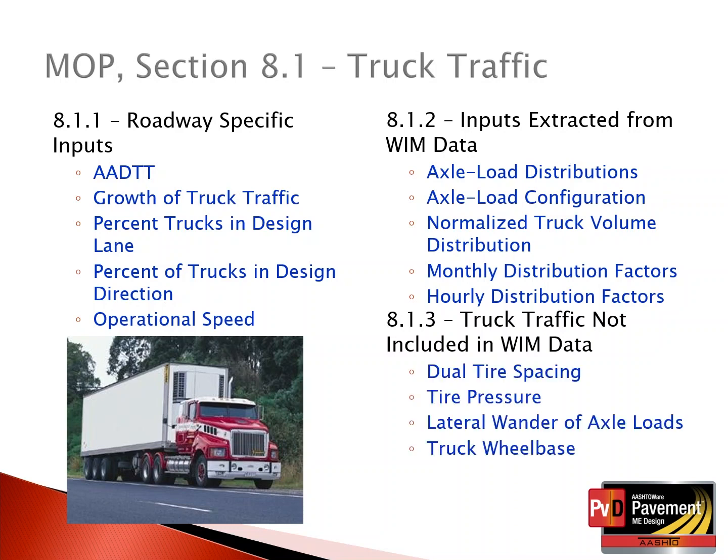Section 8.1.3 covers truck traffic not included in WIM data, which includes dual tire spacing, tire pressure, lateral wander of the axle loads, and the truck wheelbase. These truck variables are included in the Pavement ME Design software and are in a slightly different format and are discussed in more detail within this module.